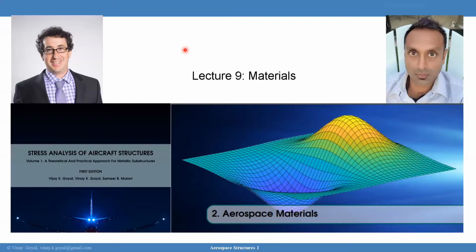In a case like that, I would probably look to see if I could find similar materials. In propellant, you want to find propellant that has somewhat similar constituents, probably a similar density, and look at what those values were, and start out by saying, well, it could be a factor of 2 higher or lower for your modulus. I would start there for making a first order guess, and then do a simple test, confirm it or refute it, and then you can go on.